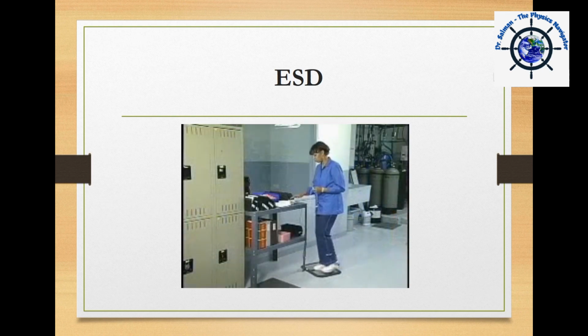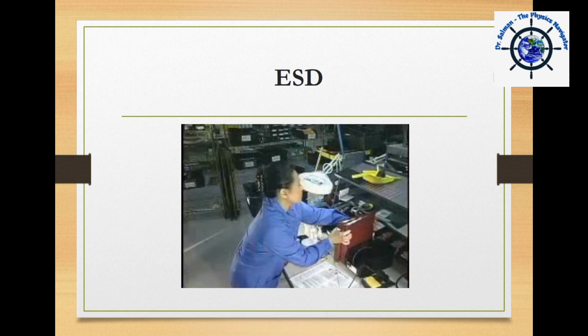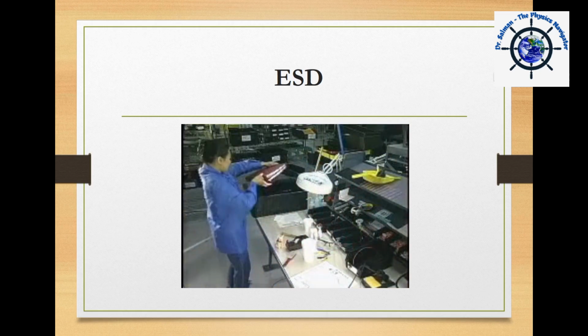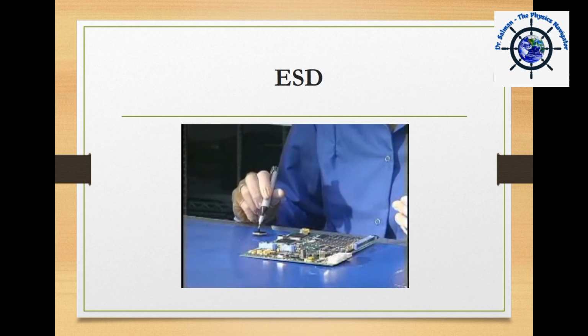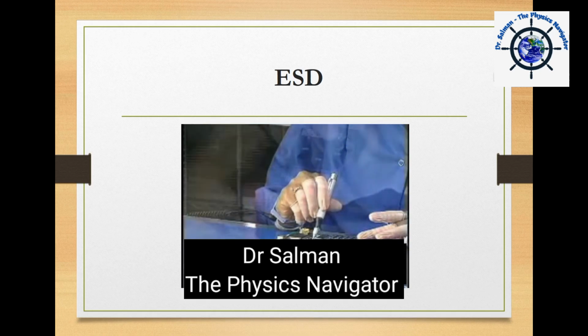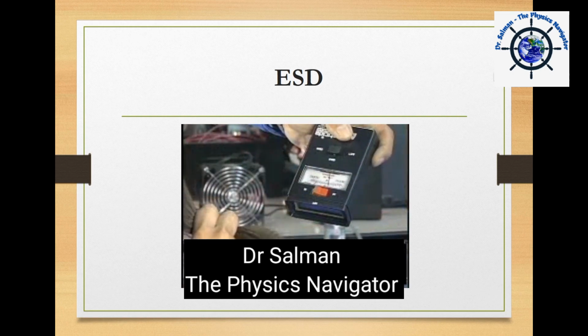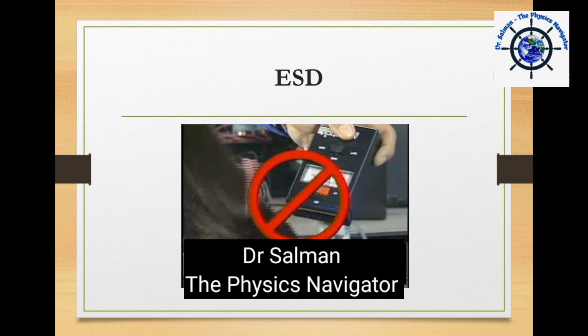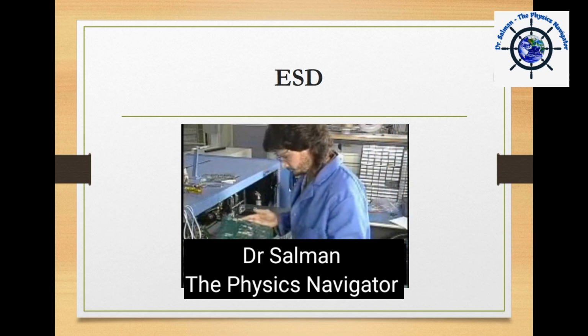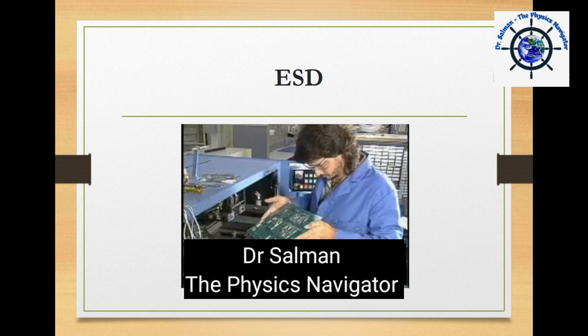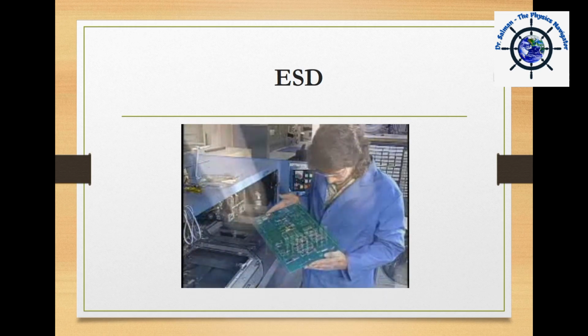This included wearing and testing our ESD personal equipment, removing unnecessary materials, using static dissipative materials, and avoiding activities that cause ESD. We know that the best way to control static charges is to prevent their formation whenever possible.